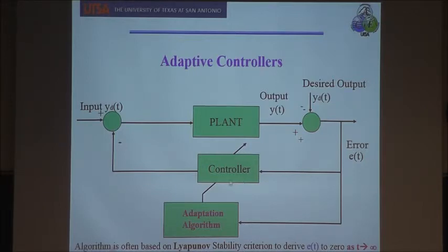And later on, actually, you can even use an expert rule. Imagine that you are the expert for a system, and you have your control knobs in front of you, and then you see the plant is vibrating or it's not doing very well. You play with this KP and KI and KD of PID control. You change those variables. Okay? So what you do is knowledge that can be used later. So we actually can mimic this from the fuzzy logic, fuzzy system point of view.